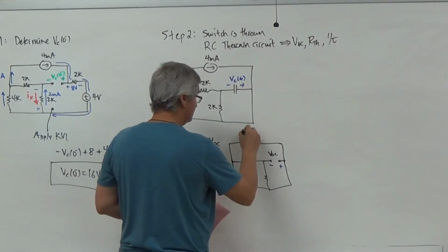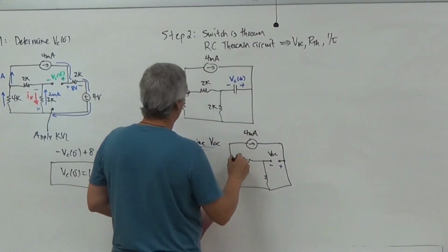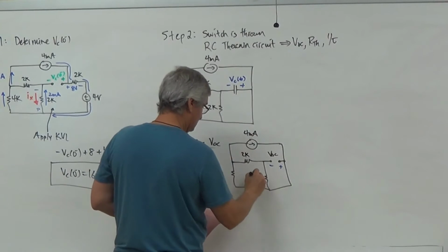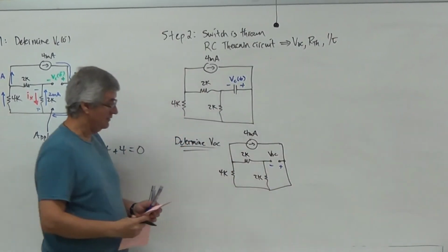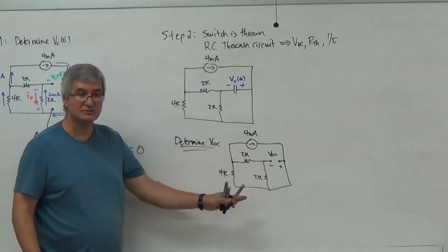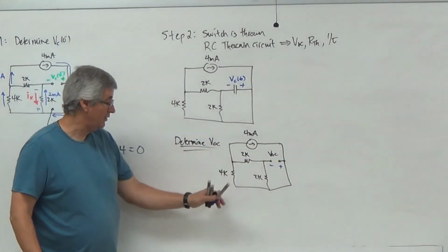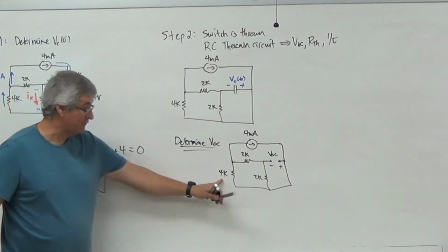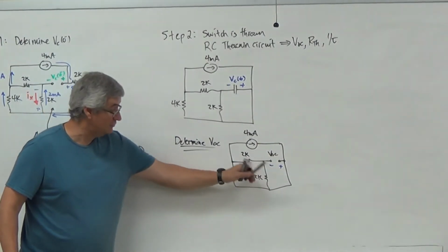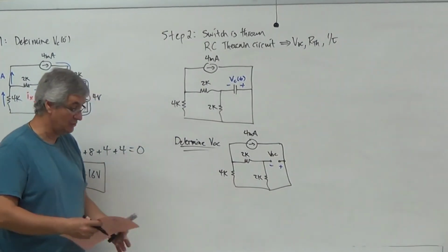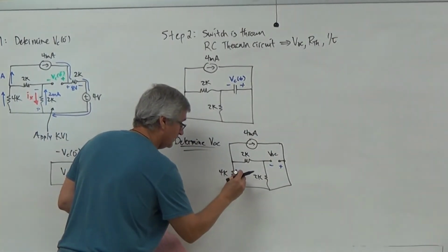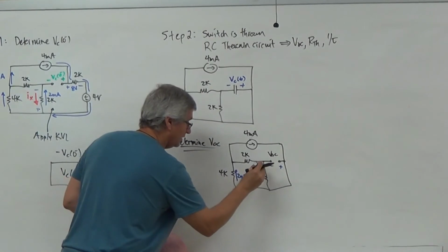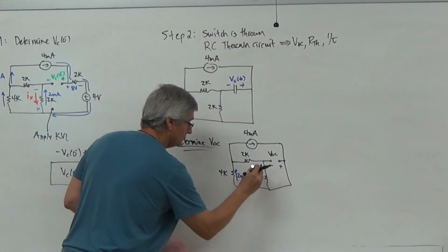So this is a nice circuit, you gotta admit, right? Because this is again very nice. Because look, there's only one branch, right? That's 4. We already saw that over here. I got a 4K here. I got 2, which is a 4K. So what does that mean? That means here I'm getting 2 milliamps. Here I'm getting 2 milliamps.